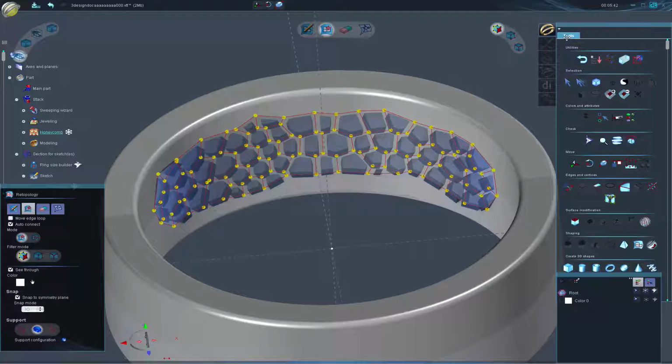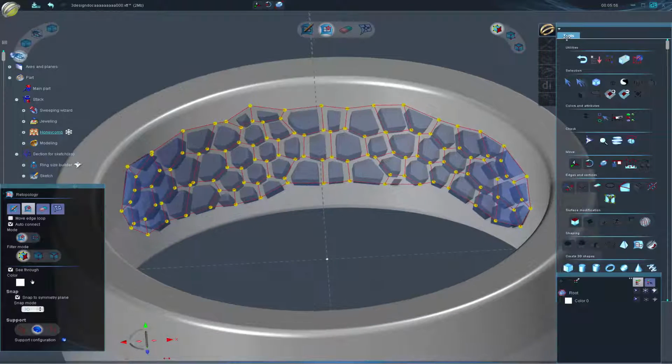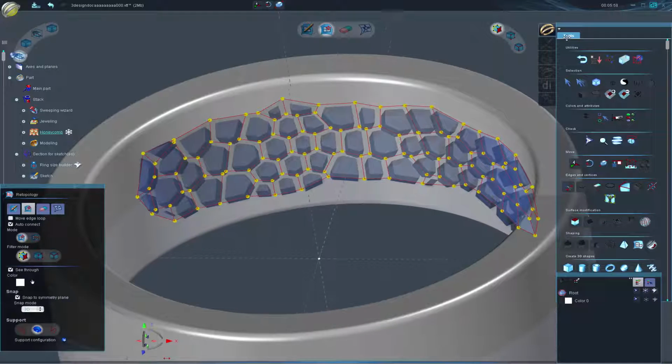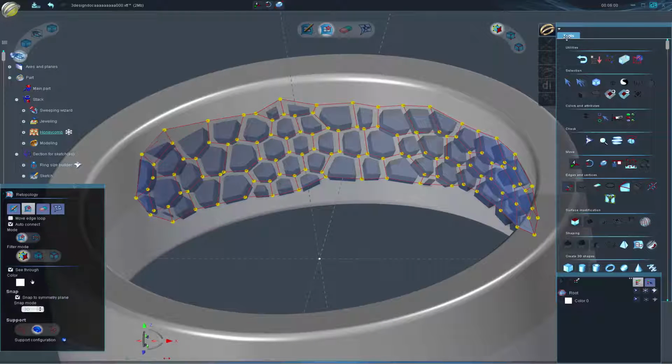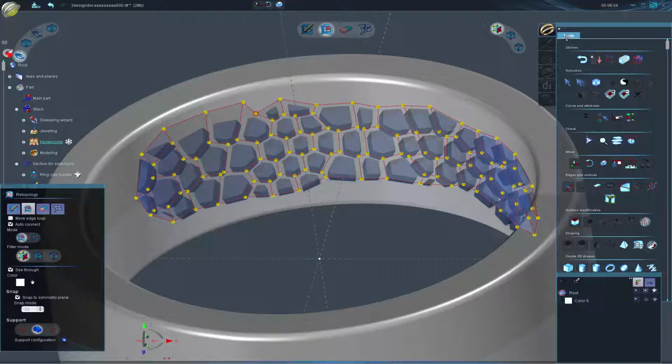If you have V2 Pro or basic 3Shaper, it's going to probably jump you right into the move tool instead. You'll have to use the move and link to support options in there for that version. So it really depends on what version you have, how it opens up. And now we can go in and just simply modify my mesh. So maybe I want this pattern on the bottom to come out to the edge instead of matching the original shape.